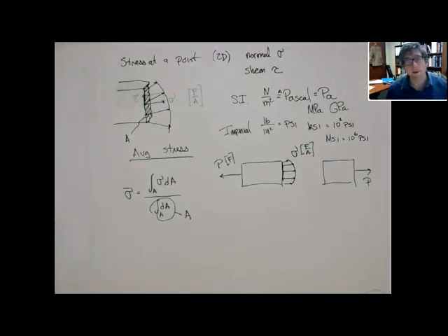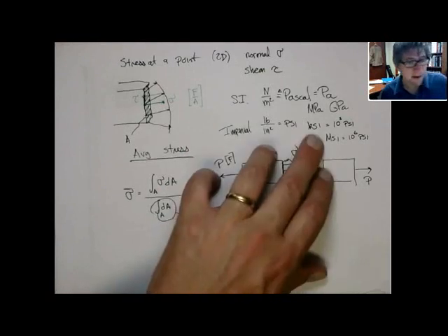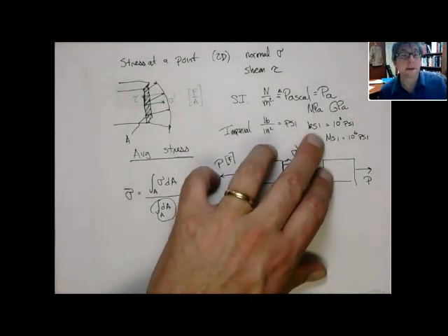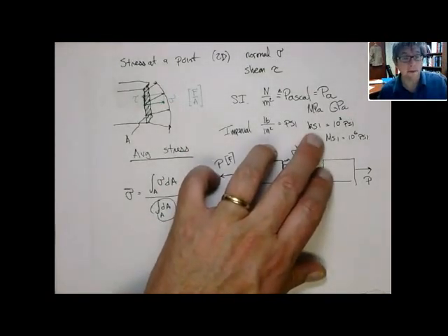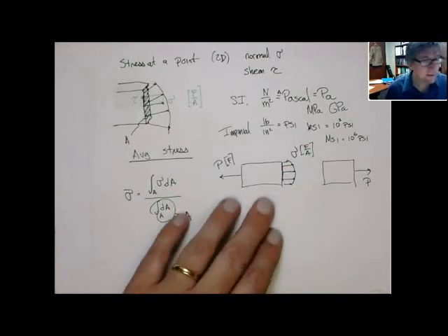So be careful about the units. Lots of practice. Those are the units that we're talking about: pascals, PSI. Okay? So be clear about KSI as opposed to a kip. A kip is a unit of force, and KSI is a unit of stress. All right, so back to this picture.